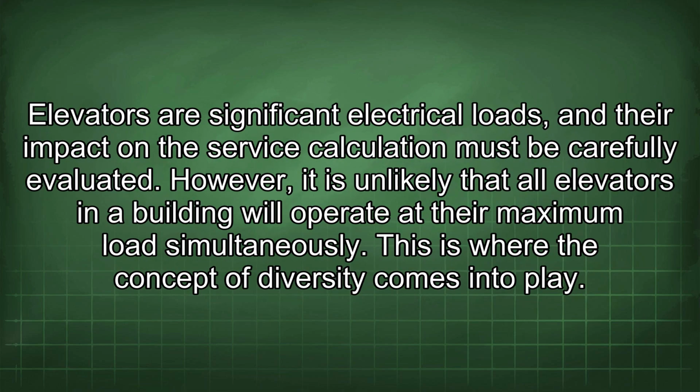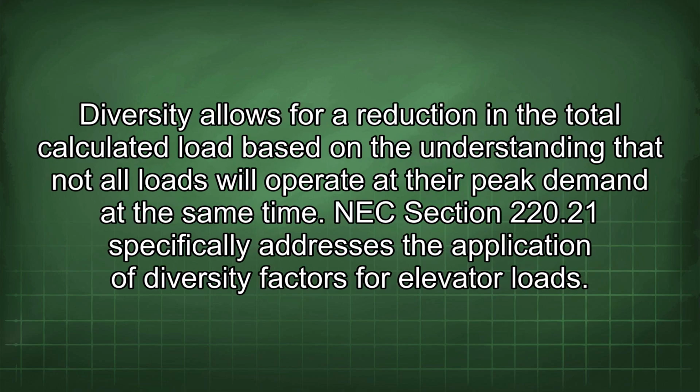Elevators are significant electrical loads, and their impact on the service calculation must be carefully evaluated. However, it is unlikely that all elevators in a building will operate at their maximum load simultaneously. This is where the concept of diversity comes into play. Diversity allows for a reduction in the total calculated load based on the understanding that not all loads will operate at their peak demand at the same time.